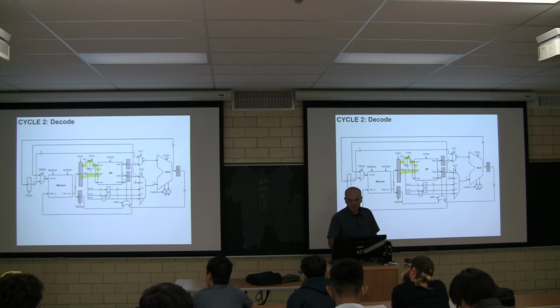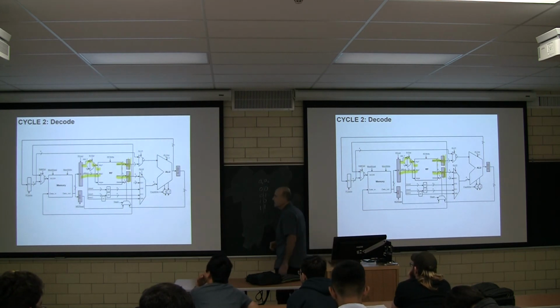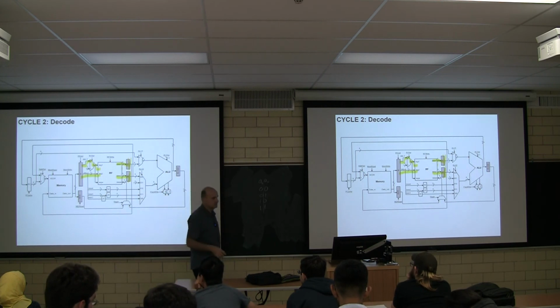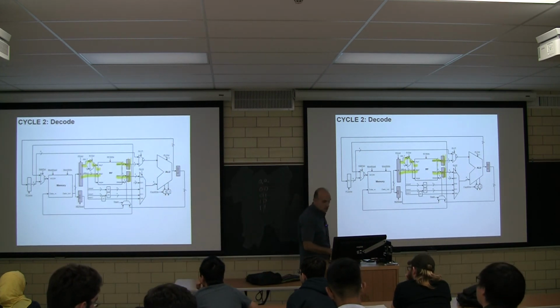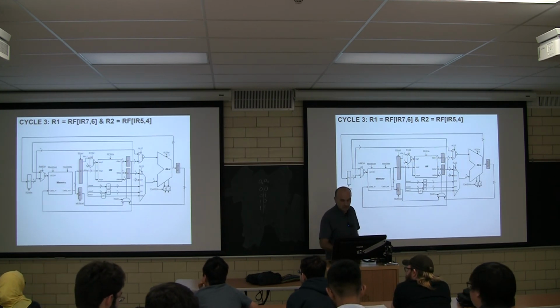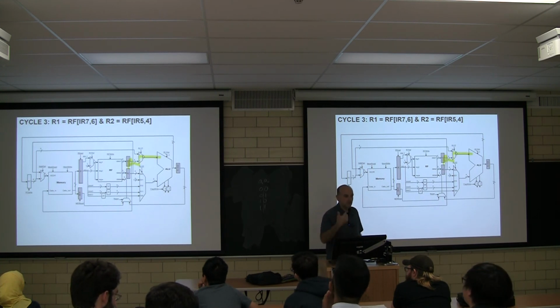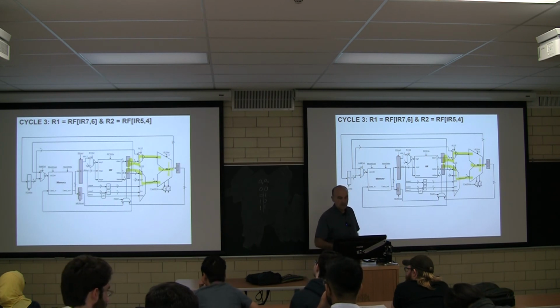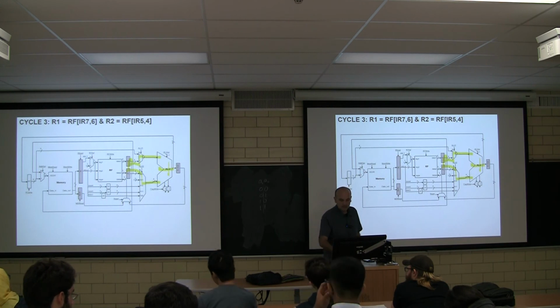At the end of the clock cycle, I'm going to give you the actual values of those 2 potential registers, and put those 2 registers here. That's cycle 2. Because we assumed that this is an add, next clock cycle that action proved to be a nice thing to have done. So we take the values from here and pass the first one to the ALU as the first operand, pass the second one as the second operand, and do an add. At the end of the clock cycle, write the result here, and then write it there.